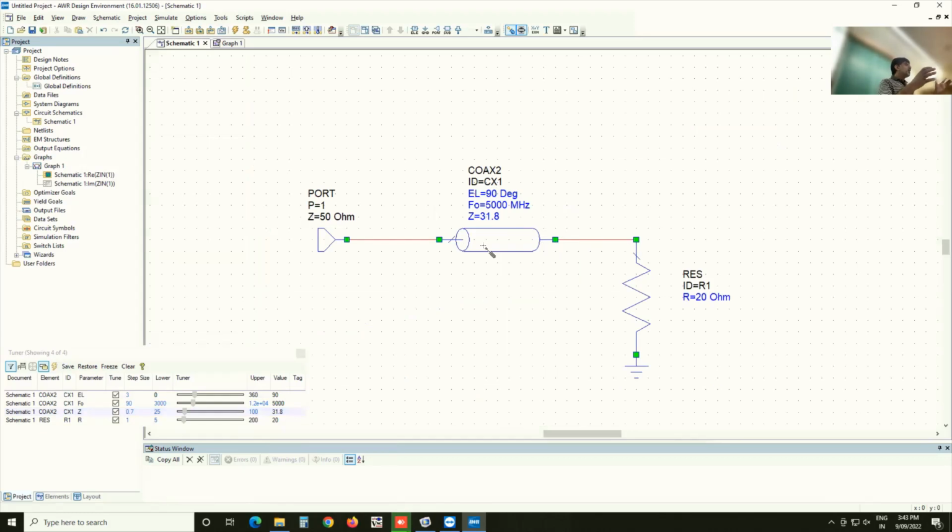Well, a transmission line has only one characteristic impedance. It's the characteristic impedance of that transmission line. What do you mean by per unit length? That's the inductance and capacitance per unit length you're talking about. See, Z naught is this, right? Where the inductance per unit length and capacitance per unit length of the transmission line give you that. But that number is uniform across the transmission line.